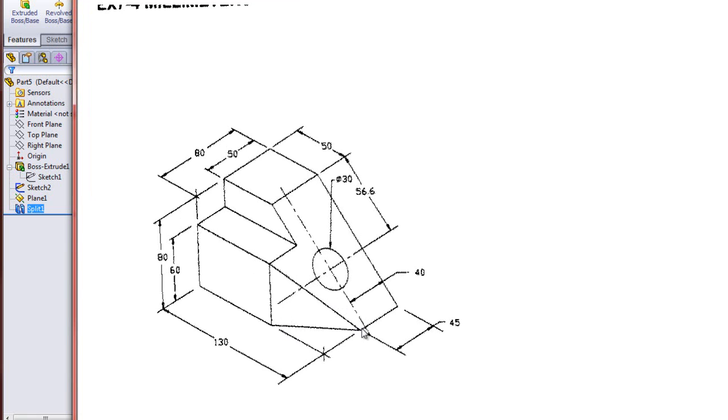I don't know what the angle is, but I do know several things. Number one is that it starts here and comes across here. So I can just create a geometry that locks it down at this point, and then cut it across over to here and lock it down at that distance. And then I can use that line to project another point to create my slice.